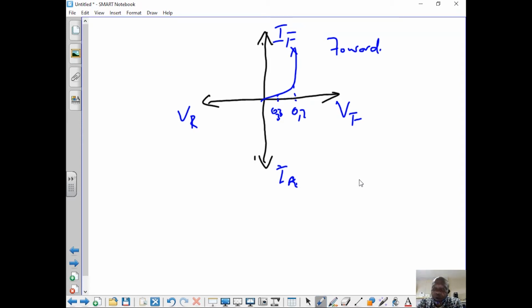And this here, when we reverse bias our diode, the broken line here tries to show you that we increase the voltage to a certain value, which we'll refer to here as V breakdown. Our diode starts to conduct in here. A lot of current flows. Now this, we're going to talk about it. This is when it is reverse bias. Here on the first quadrant, it's when it is forward bias. Now remember, a diode gets reverse bias when the voltage on the anode is more negative than it is on the cathode.